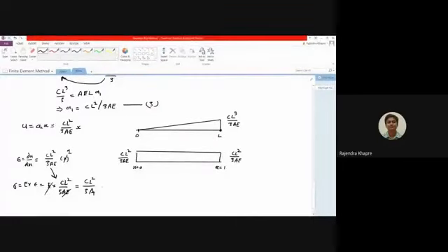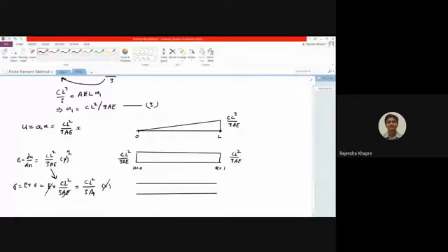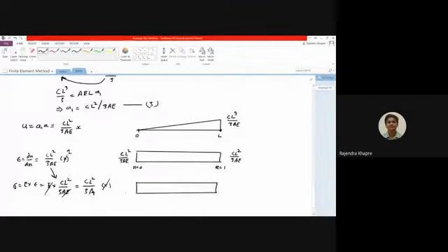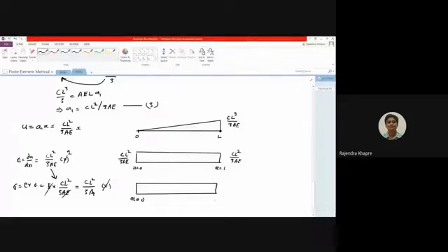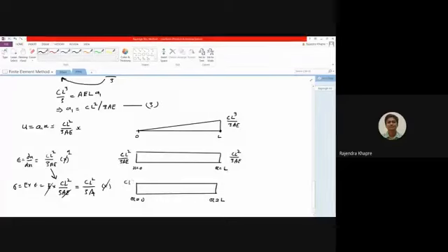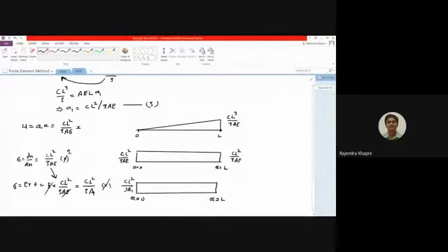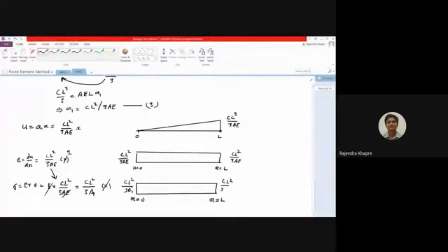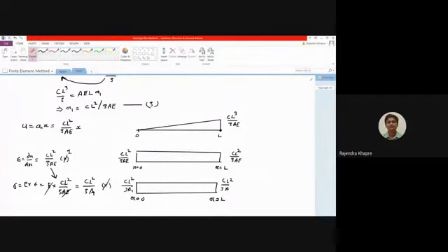So in this component also, the X component is not at all there. So what is the meaning of this? That is, irrespective of the location, you will always get a stress as a constant value. Here X will be 0, here X will be L. And the value of the stress will be C L square divided by 3 times A. Here also this is C L square divided by 3 times A. Sorry, this is not A1, this is only A.